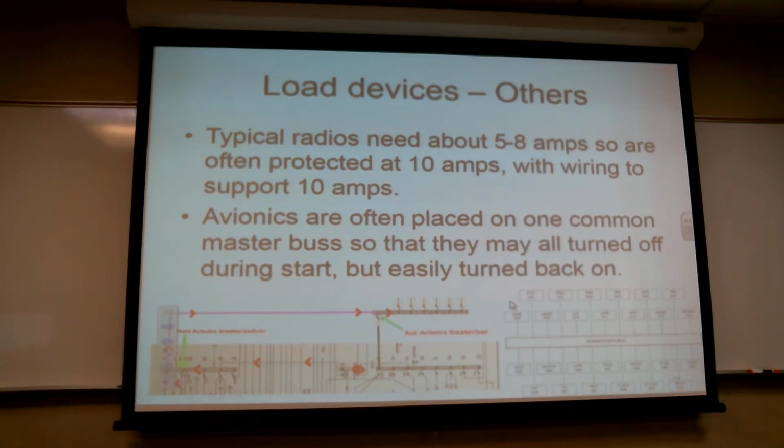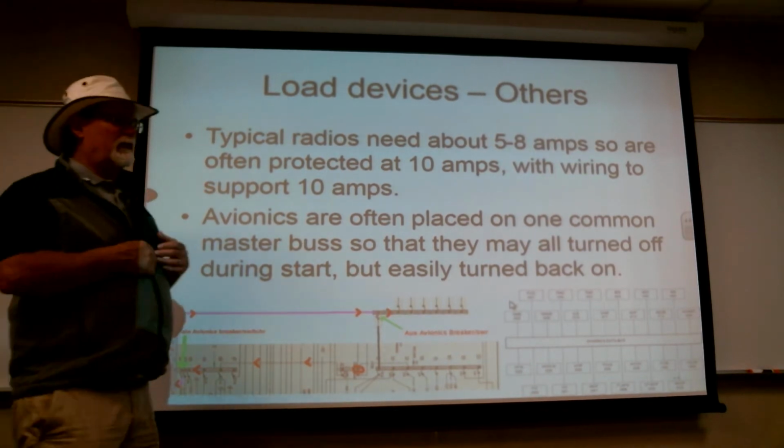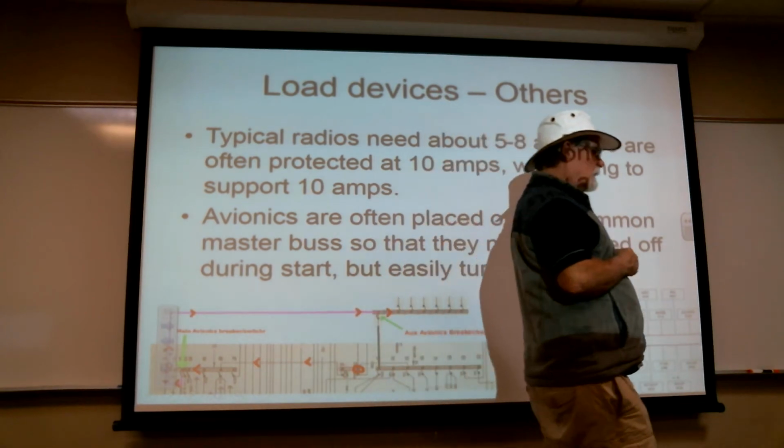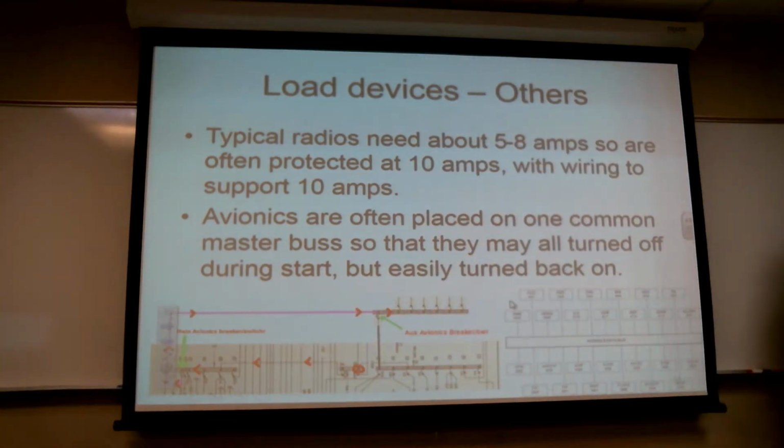The installation manual for an avionics component that meets a TSO usually stands on its own, and then you install it either through FAA Form 337 and/or somebody out there may have engineering data as well, or if you're operating under your radio repair station license, you yourself may be certified to use that data as the authority for installing it.